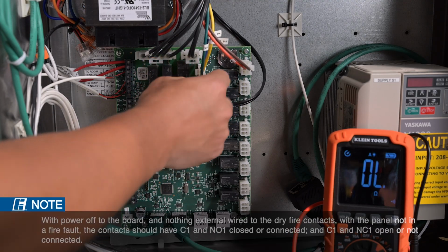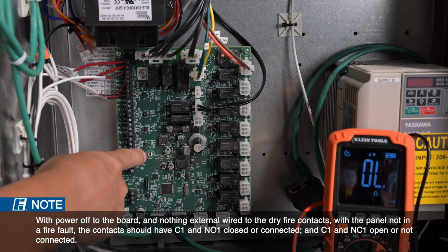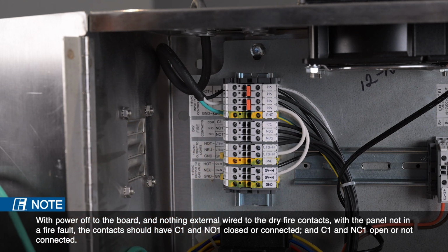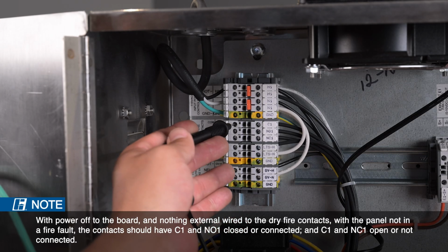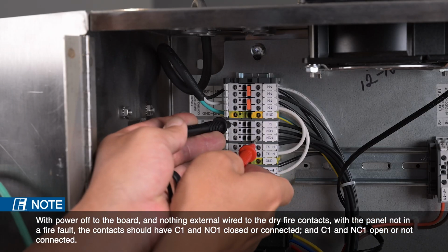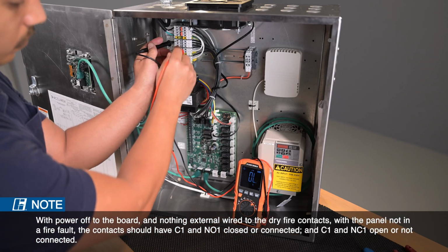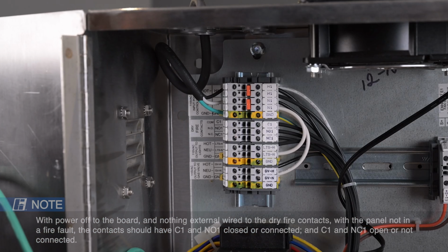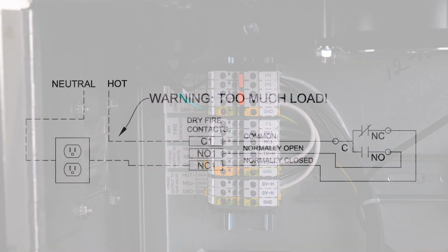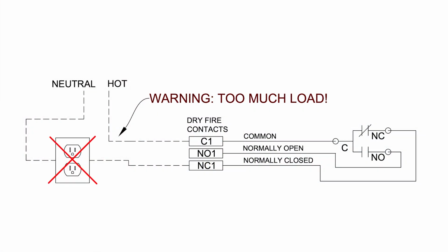Now, with power off to the board, and with nothing external wired to the dry fire contacts, with the panel not in a fire fault, the contacts should have C1 and NO1 closed or connected, and C1 and NC1 should be open or not connected. If the contacts do not match this, please contact tech support and have the serial number of your control panel for reference. This relay is rated for 8 amps and up to 250 volts AC.